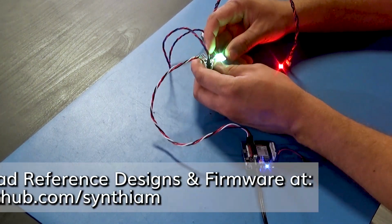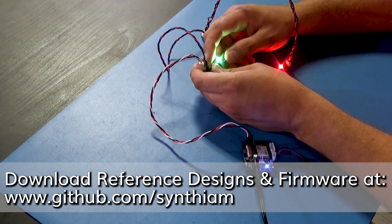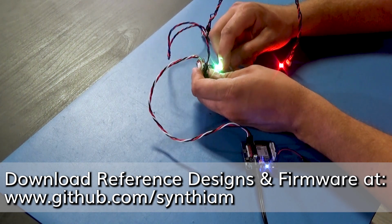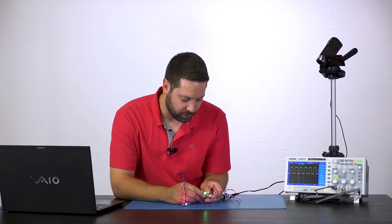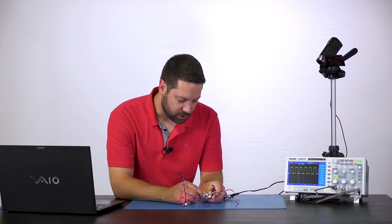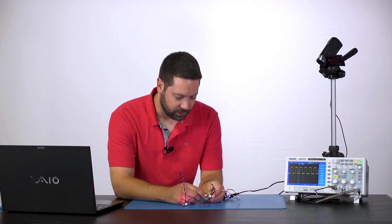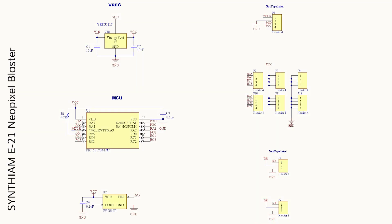On board the Neopixel Blaster, we have a PIC chip. It has custom firmware on it, a 5-volt regulator, and obviously the Neopixel LED on there, which is a WS2812B. So let's look at the schematic and see what this all looks like. In the schematic here, you'll see there's the 5-volt regulator, so it could regulate up to about 1 amp.